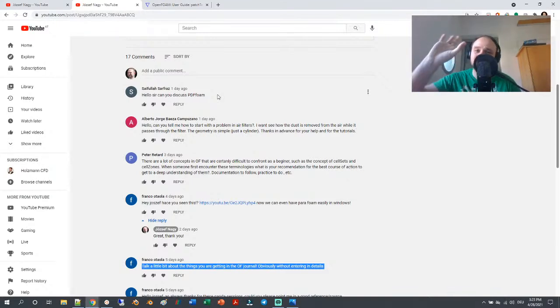So for example, if you are doing AMI and you rotate your cells, then you select a certain cell zone that you call, for example, a rotating zone, and this selection of the cells is called cell zones. The face zones on the surface of the AMI are also a selection of faces, and then with this selection you convert the faces to AMI, and then they can communicate between each other. And a cell set is a more limited version of a cell zone, kind of like that.